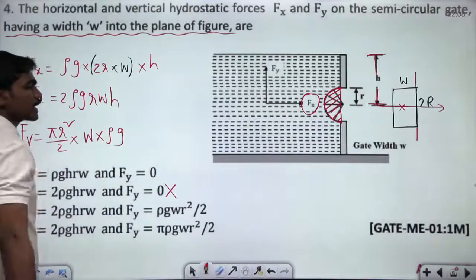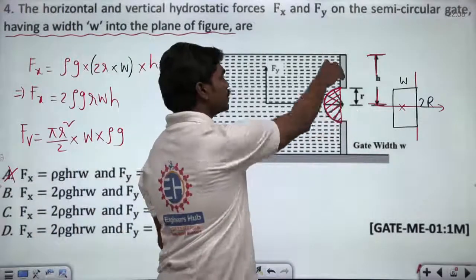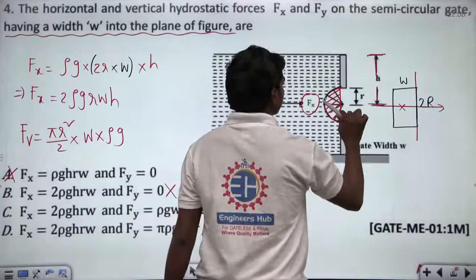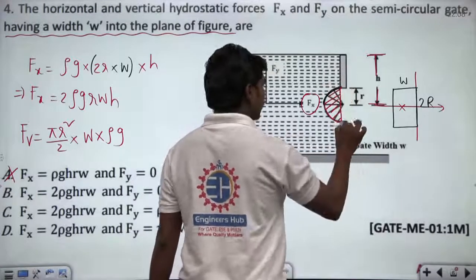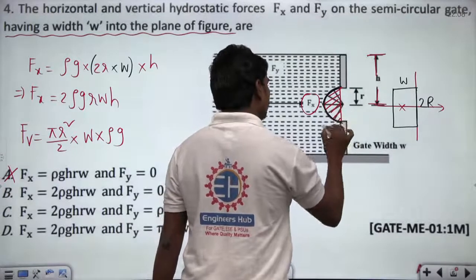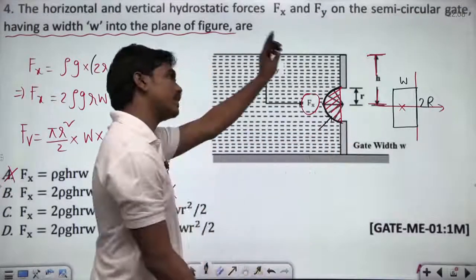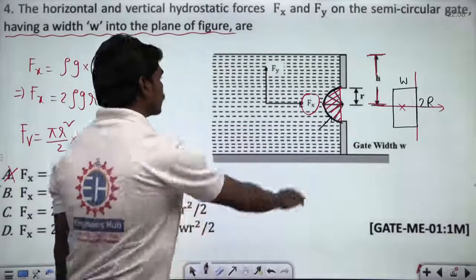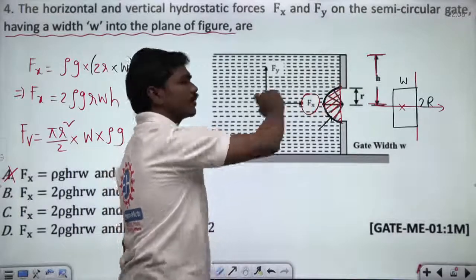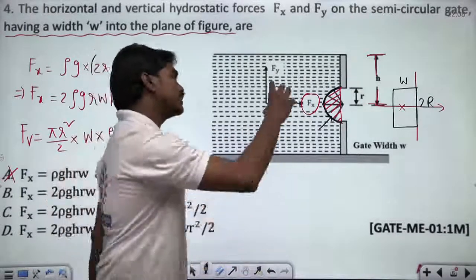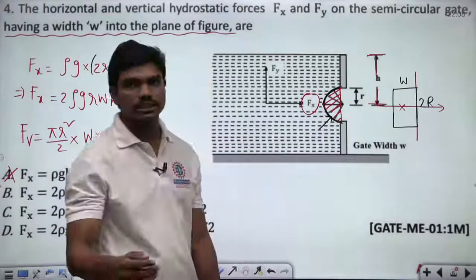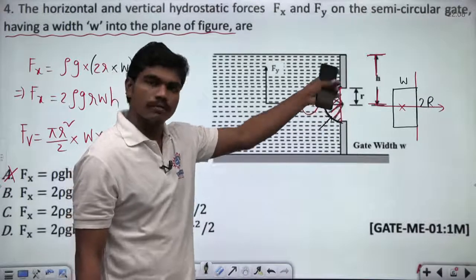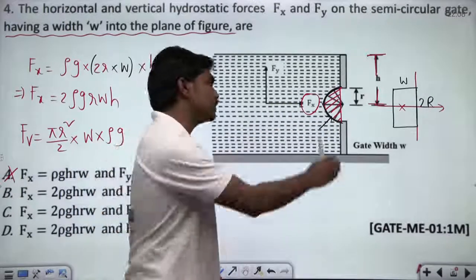So this is basically the net vertical force acting on this plate, because on this portion the weight will be in the downward direction, and in this portion the fluid pressure force will be in the upward direction, so the vertical component will act upward, correct? So the total net effective force is equal to this cross section area into width of the plate. Later, in the fourth module, you will see the buoyancy force is equal to density into gravity into volume displaced by the solid, correct?